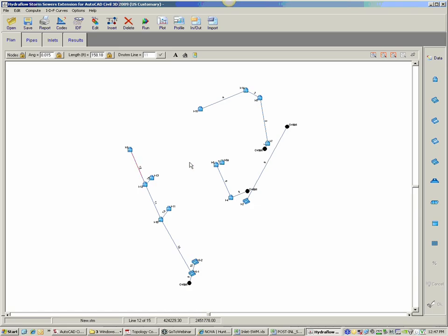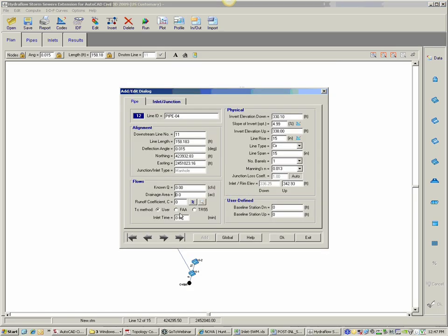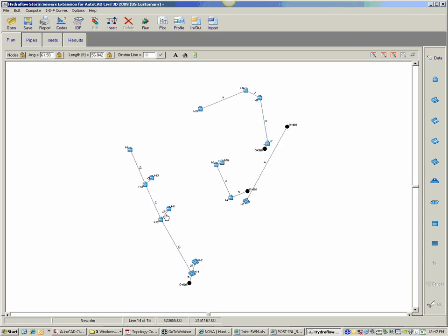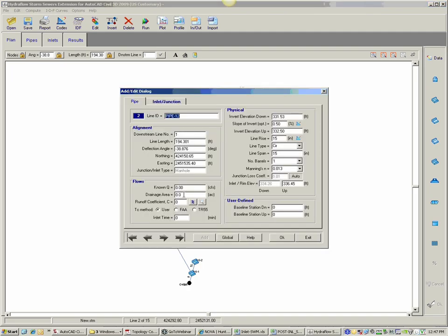Okay, so there's a good amount of work in design and setting this all up to model your conveyance system. One of the pieces is that you need the drainage areas, right? You don't have any drainage area or C coefficient for any of these inlets. So what we're going to do is use that Excel file that we have, that inlet one, to push all the drainage areas into this HydroFlow file. As you can see here, if I click on any given inlet and hit data, I don't have any drainage area or Manning's or